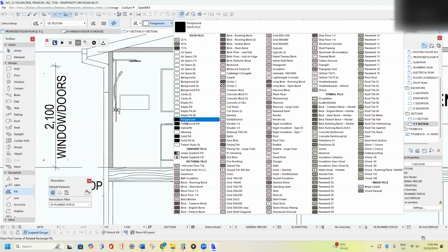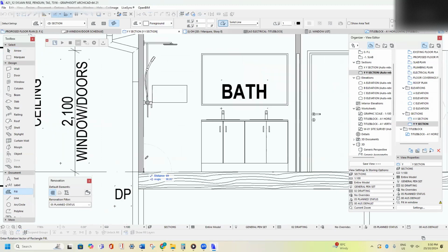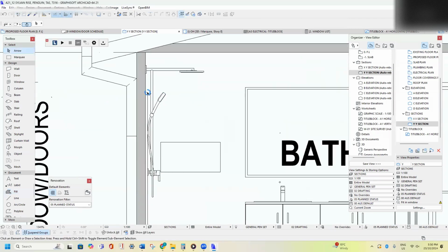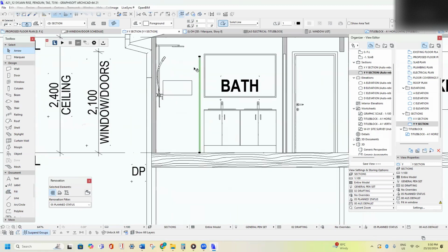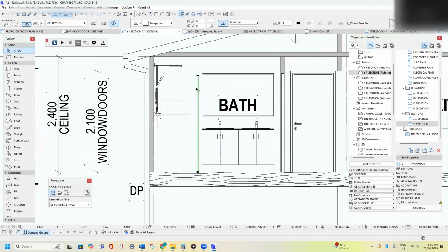Actually, I'm just going to grab a foreground, a white fill. If I click there and hold Shift and go up here and draw and type in 2 meters, then bring it 20 mil off, press Escape, Control D, locate that 900 off. So that denotes the shower screen.